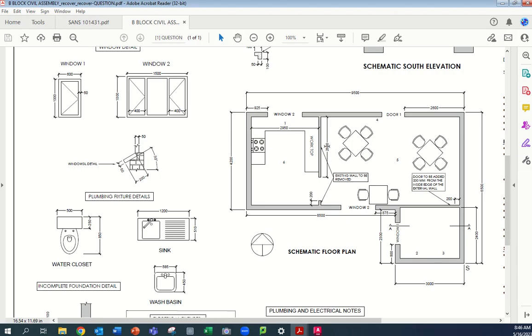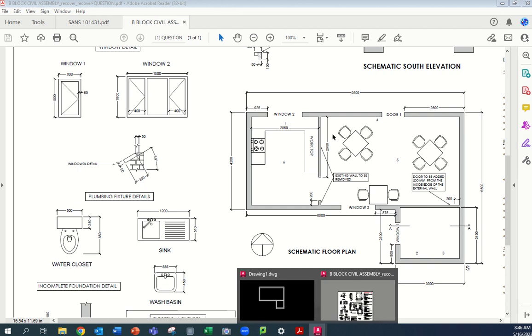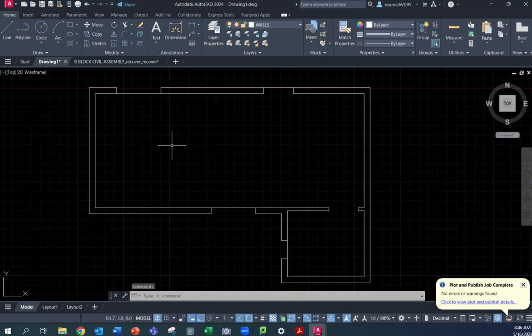renovations that we need to do here, and that's this wall. Right, the distance of the wall from the inside edge is 2950 across, so we're going to come back to CAD. Now this is a removed wall. This is an existing wall and it needs to be removed. So we're going to draw the wall in with detail, and then we will add the conventions to reflect the removal of that wall. Okay, so the detail will be there, but it will be with a different convention.